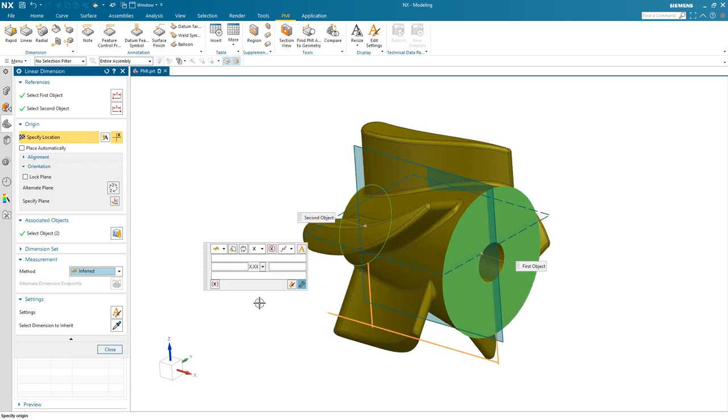Notice the system sets up temporary planes. One of them is the work plane. This dimension cannot be properly measured in the trimetric view, so what NX does is it orients a plane that's most appropriate between those two faces to set that dimension on.